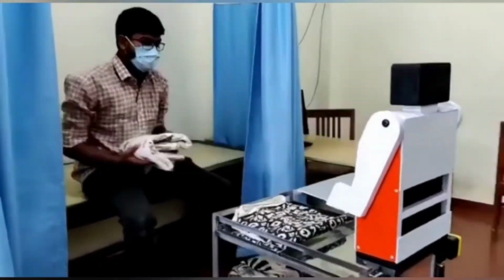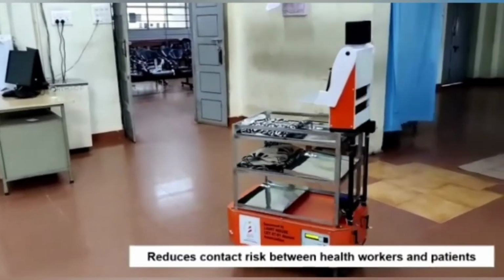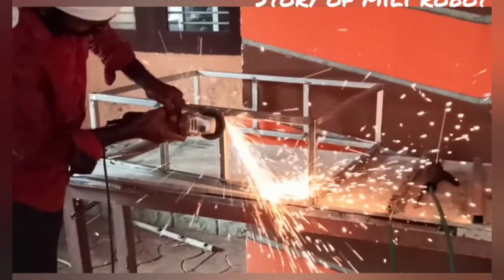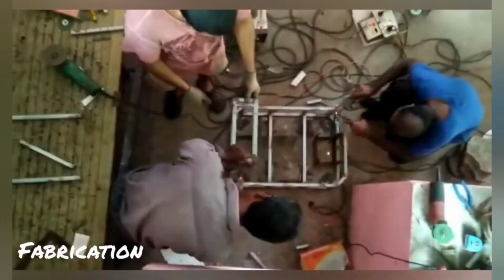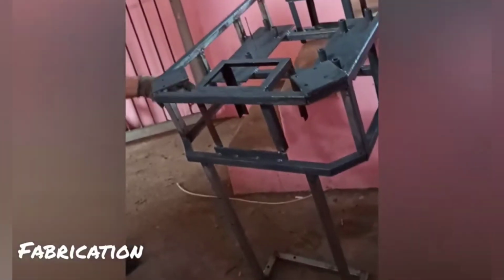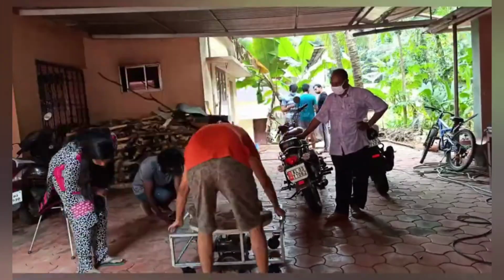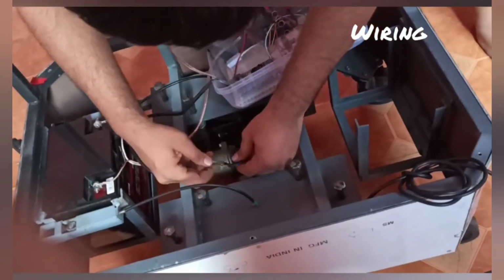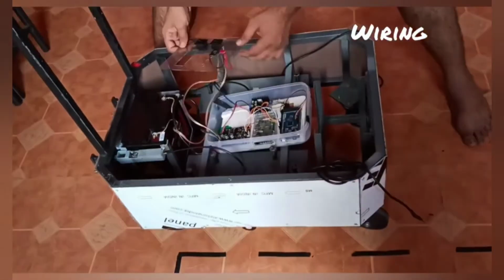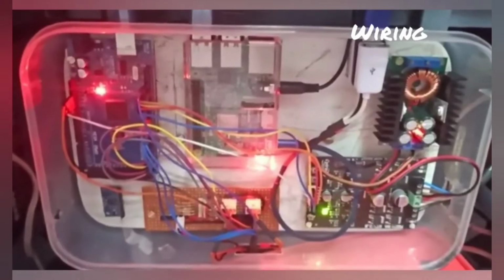Next, I will be explaining the fabrication stages of the real robot that we have implemented in Medical College Hospital, Trivandrum. Here, the main frame of the robot is made using GI square pipes. We chose a design that fulfills the purpose of the robot, which is to have a payload of above 40 kg. The controllers used were Raspberry Pi, but the main processing and motor control were done using Arduino Mega. Our robot works on the ROS platform with a combination of sensors to navigate to the desired location.